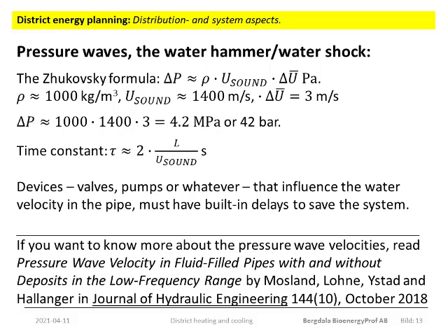Another possible cause of sudden pressure shocks is cavitation, as mentioned previously. Cavitation means that steam bubbles form in a low pressure zone. And when the pressure is increased again, these bubbles will implode, they will collapse. And that will cause shock waves, pressure waves, as the water rushes in to fill the cavity that was previously full of steam. So not only flow blockages but also cavitation are risks from local low pressure zones in the network. So low pressure zones must be avoided.